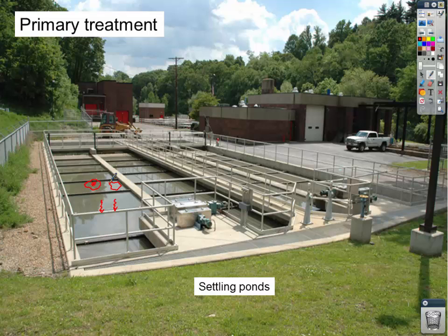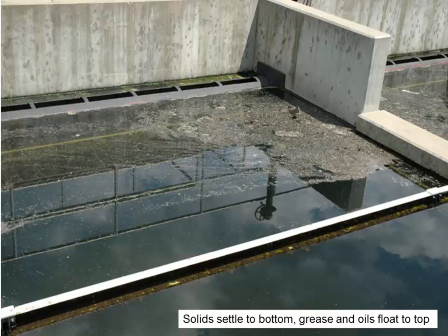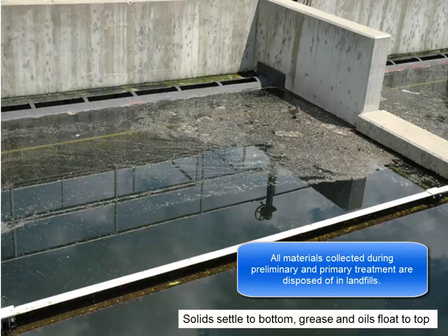So think about things that go down the drain. You're cooking food and you use olive oil in the pan. That gets dumped down the drain. That goes into the sewage system. All the restaurants in towns, the greases and the oils and the fats, anything that goes down the drain, this is where we want to get those things separated. So let's take a look at a picture. Here's the greases and the oils floating to the top, and then we have some sort of scraper that will scrape this stuff off, and you have to dispose of that separately.